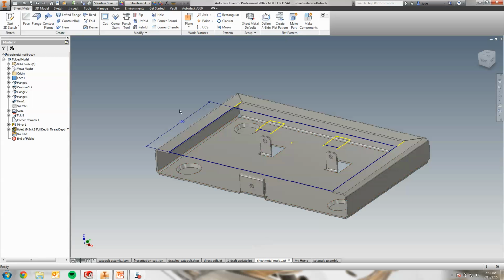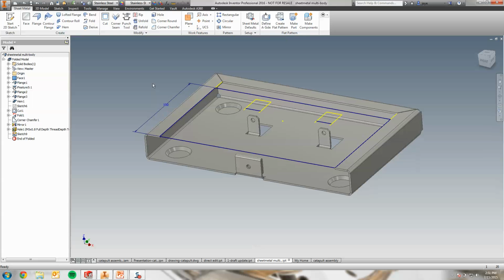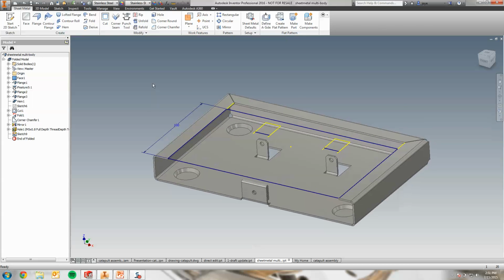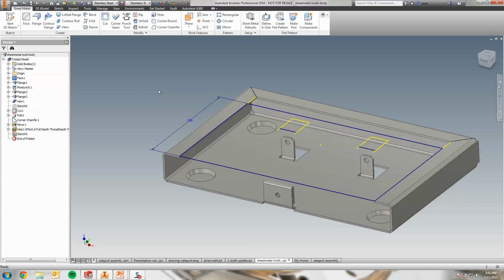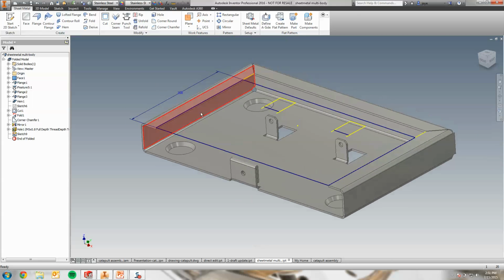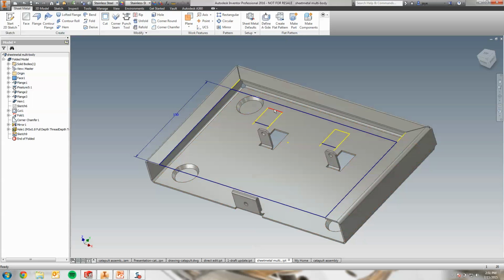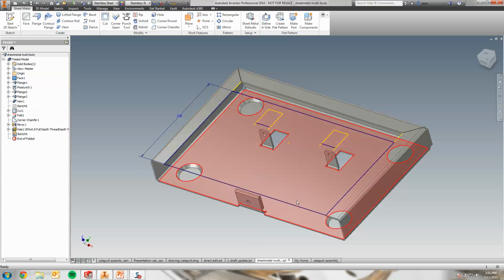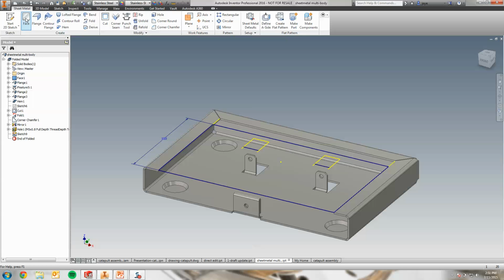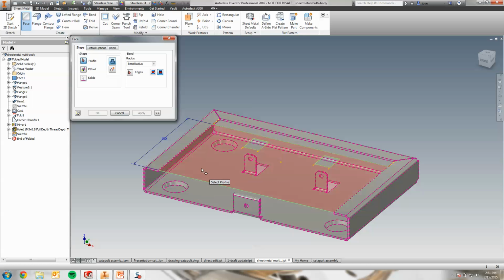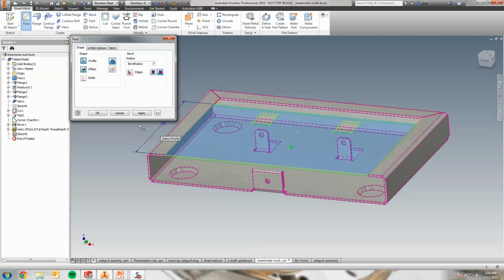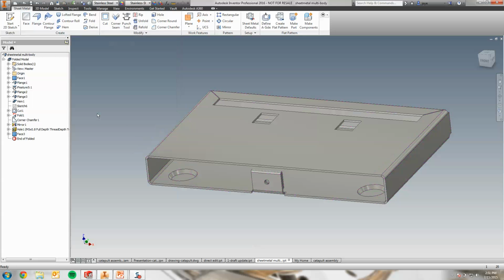Bringing up a sheet metal part. Now within the sheet metal files, you can create multi-body parts within sheet metal. So I could have 2 different sheet metal parts. So ahead of time here, I did create a sketch on top of this face here, and you see I have some projected entities here, and I have some sketch entities. So I can go into the face and click on that, and I'll just click OK.